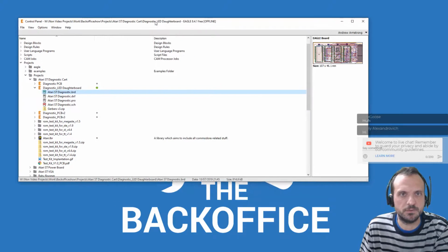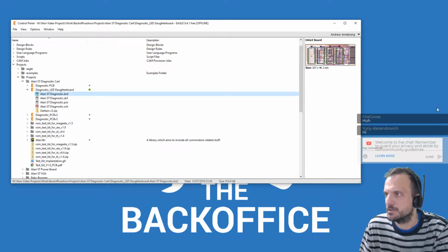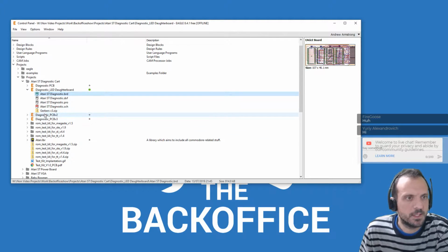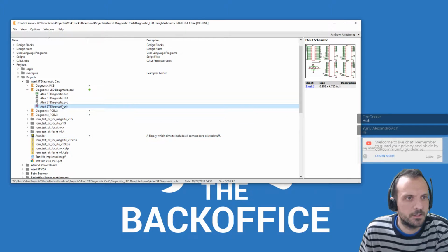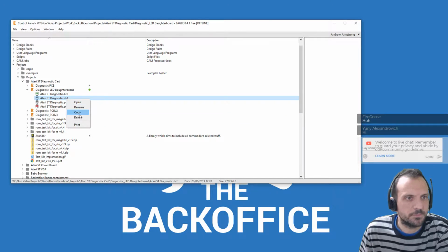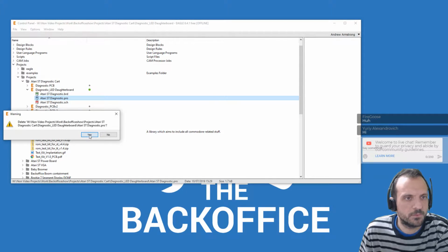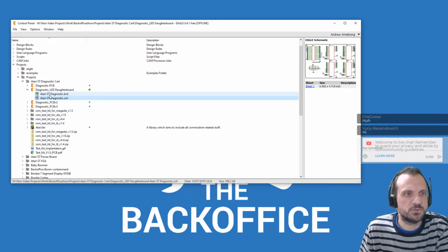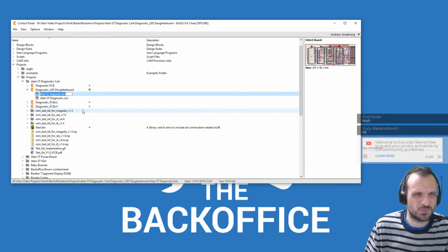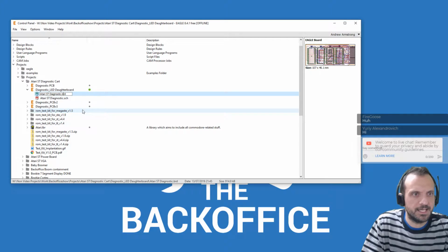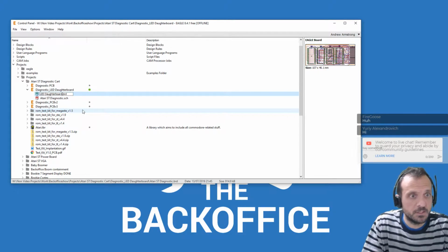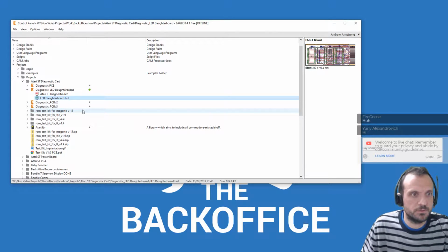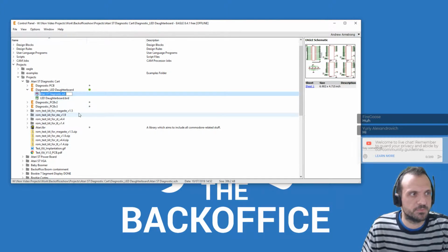Again, this is in Eagle version 8, free for most people. Let's delete the old Gerbers as well, because the last thing you want is any of the old stuff going out by mistake. So it's called Atari ST Diagnostic. That was the name of the actual main board, but I'm going to call it LED Daughter Board, and then change that to LED Daughter Board as well.